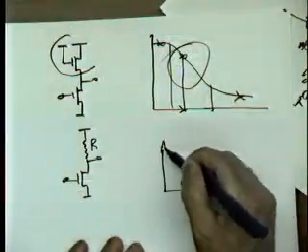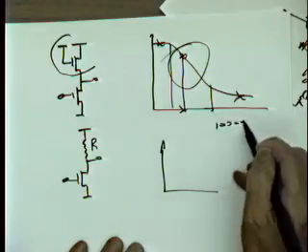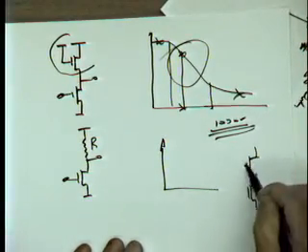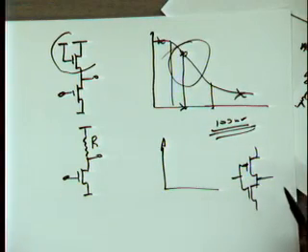You do that, you will see that you can have a sizable disruption. In about 2 inverter stages, it's going to be gone. It's really quick. But it depends upon the gain. If I have a gain of 200, let's say, if I make a gate which runs at 100 millivolt supply voltage in sub-threshold or something like that, you will see there your gain is a lot smaller.